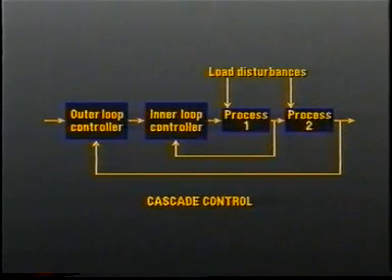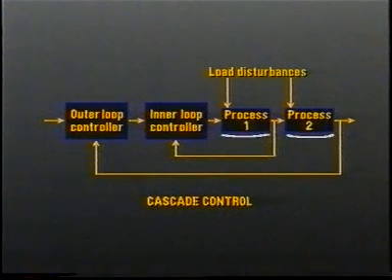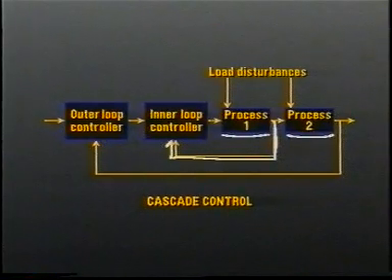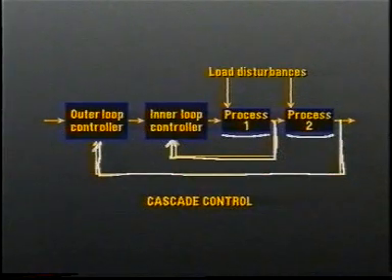Cascade control describes a configuration used to control a process that really operates as if it were two processes in series. In this strategy, two feedback loops are used. The set point of the inner loop, which controls the first process, is furnished by the output of the outer loop, which controls the second process. Through the use of the proper controls applied through proper strategies, extremely effective control loops can be designed and, more importantly, implemented in the field.